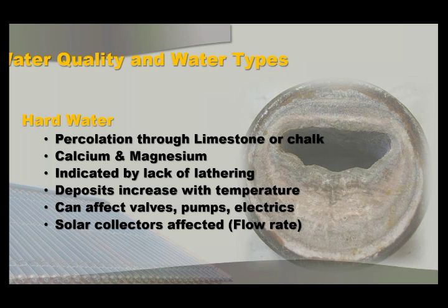Okay, so let's get into this session. Water quality and water types is the heading, and let's look at hard water and the effects that hard water has on our system. To be honest with you, for many years of my career, I didn't bother about whether I'm in a hard water area or not. I mean, if I put some pipes in your property and you've got hard water, that's your problem. Well, it's not that simple, especially when we're talking about solar, because it negatively affects the performance of that solar, and we have the responsibility to make sure that the thing works properly.